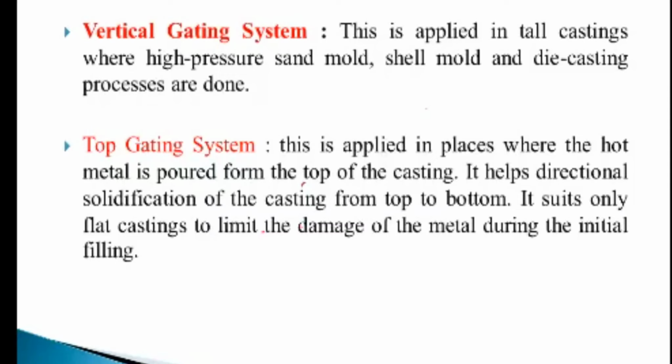What is the advantage? Suppose during solidification shrinkage takes place and this shrinkage is large, your dimensional accuracy will go off. So at this position, the other metal which has not frozen so far will flow up to there and provide the required amount of molten metal at that point. So it will not get a defect. That's why directional solidification is what we must achieve in the design.